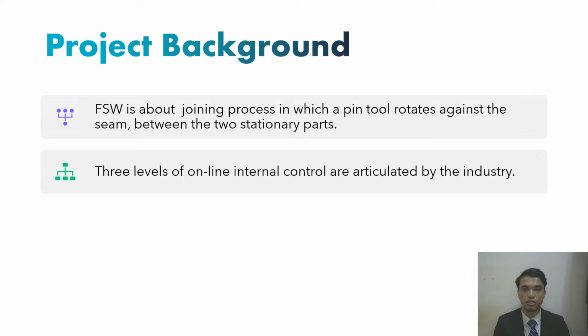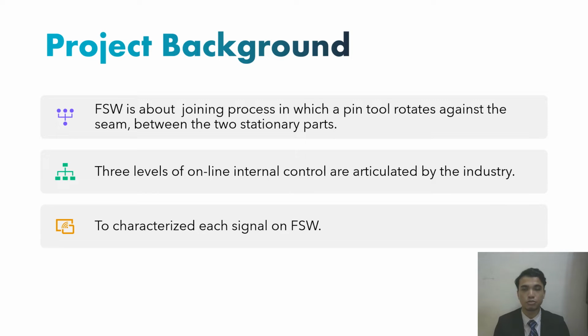Within the second level, one should be able to locate the kind of fault and the reason for faulty weld production, like change in the welding process, including disturbance in shielding gas delivery, changing in wire feed rate and welding geometry, etc. Within the third level, one should be able to correct welding parameters during the welding process to ensure weld quality.